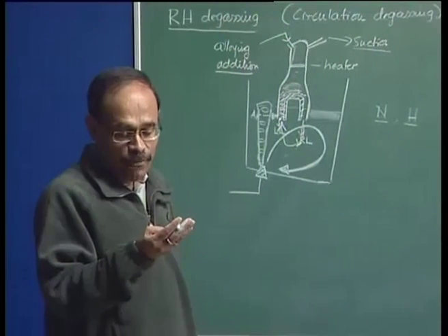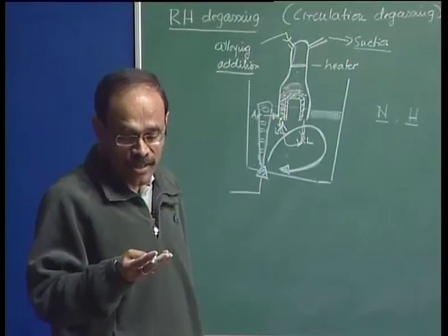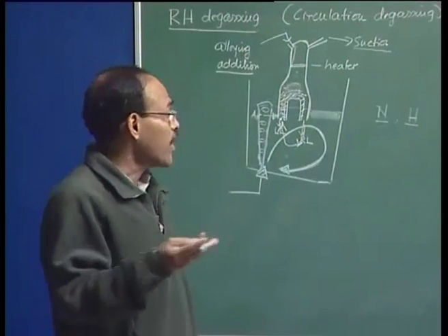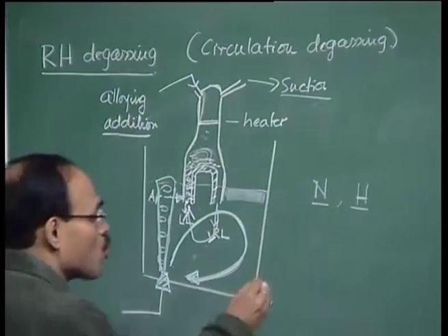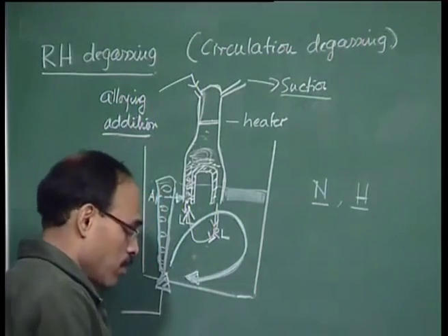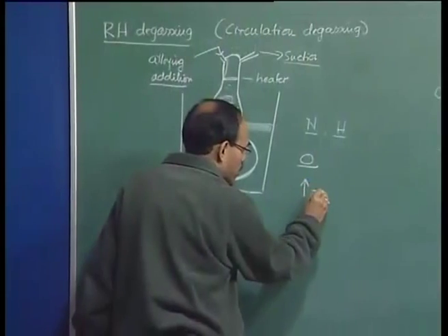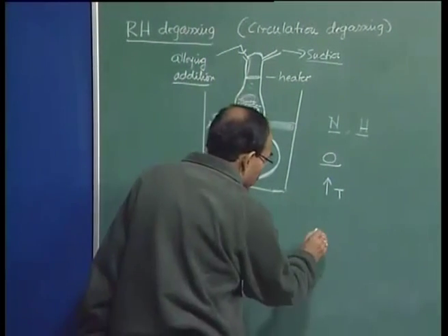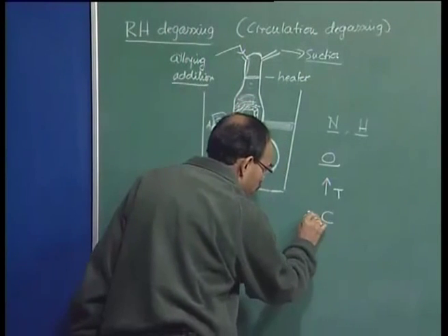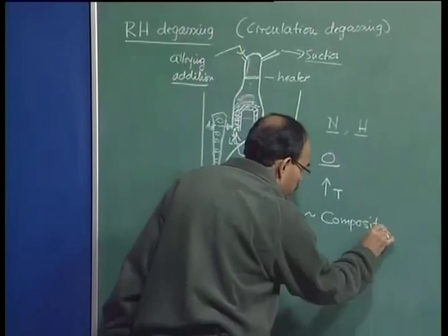So, if you look at it from the furnace steelmaking operation, we have furnace steelmaking, then the deoxidation operation, then the ladle metallurgy operation, and then finally the degassing operation. What we have been able to achieve is that we have reduced the oxygen content of the melt through degassing. We have increased the temperature of the melt, and through LF operations we have been able to adjust the composition correctly in the LF itself.